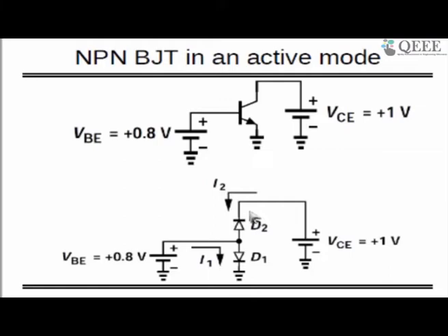That is the only way, and you have to keep the P region very small, so that all the electrons coming from the N plus side will move to the N side, or be collected at the N side region. Your downside, which is N plus, is emitting lots of electrons, and the N side is collecting lots of electrons. That's why we call the downside N plus the emitter, and the top side the collector.